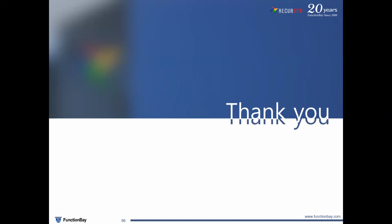So the inputs of interest are the stiffnesses and damping related to all 6 of those degrees of freedom. And the stiffnesses can be defined as linear or nonlinear. Nonlinear stiffness can be defined with a spline, and you can have a different spline for each degree of freedom. So I think I answered that question.